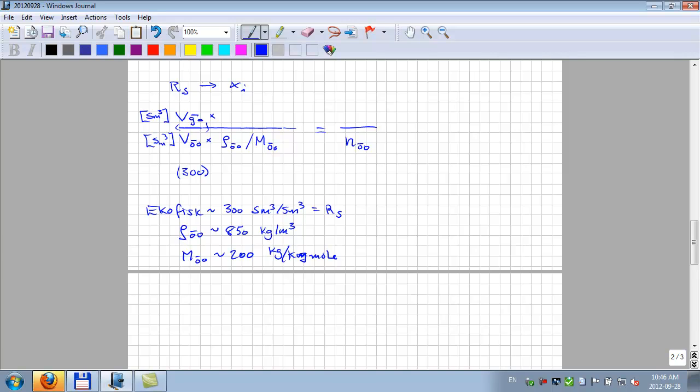There's some magic number out there. Any surface gas volume, 23.68. So we have to divide this by 23.68, and that's in standard cubic meters per kilogram mole. Okay, and that gives us surface gas moles coming from the oil. So at least directly we can calculate the ratio of moles of surface gas to surface oil, right? That's a starting point. It's not X of I, but it's a starting point.